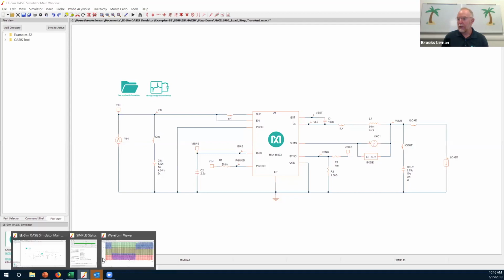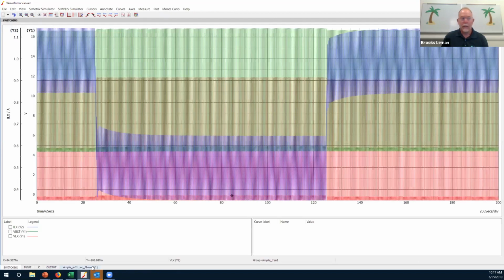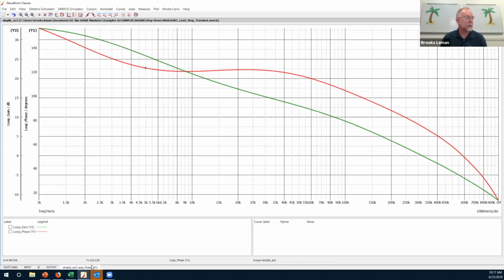You can get output impedance, PSRR, and you get this from the same model. The same model is used for both time domain and frequency domain in effectively the same simulation session. Very powerful. SPICE Bode plots require extraordinary extra time-consuming effort.